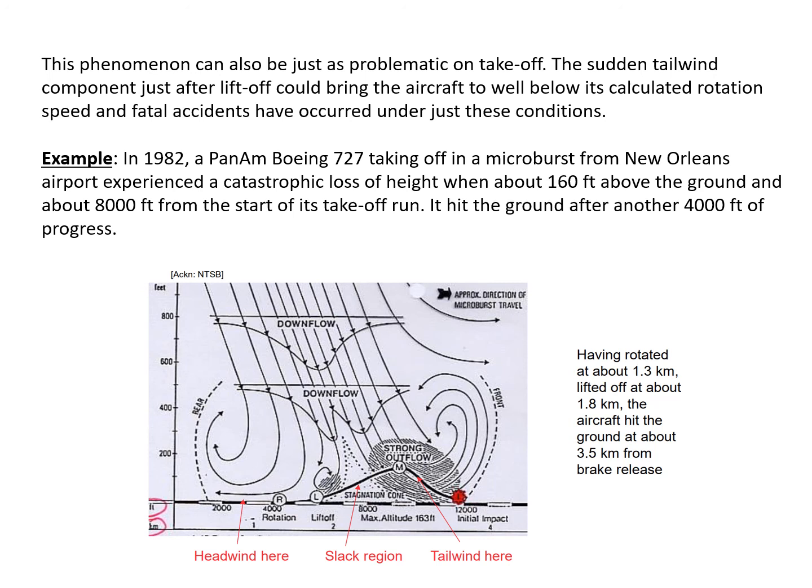I hope it's clear for the current analysis of the aircraft response to a longitudinal gust. So from headwind to tailwind, and that will cause longitudinal instabilities. Since the short period oscillation will be damped out very quickly, our focus is placed on the phugoid. Okay, so let's finish this mini lecture.